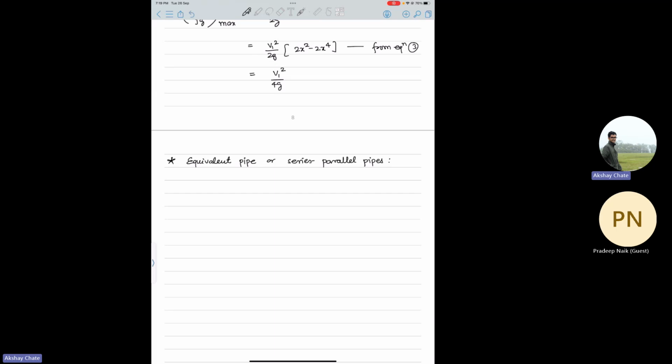So basically, if you have seen, let's say you have one pipe. I'm not drawing the pipe because that takes a lot of time. Let's say you have one pipe, it is getting divided into 3 pipes like that, and then again it becomes a single pipe later. So these 3 pipes which are shown by a line here, they are in a parallel connection, and each pipe will have some F1, L1, D1, right? It will have F2, L2, D2. This will be F3, L3, D3.